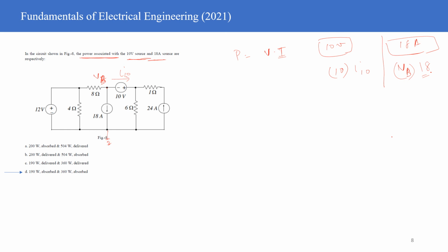I think it should be obvious to you by now, right? Then how do you figure out the individual things? Like how do you find the numerical value? You take again the KVL and the KCL, like those things are going to remain the same, right? So you have three nodes with you, VA, VB, and VC, and then you write the KCL equation at these three nodes.